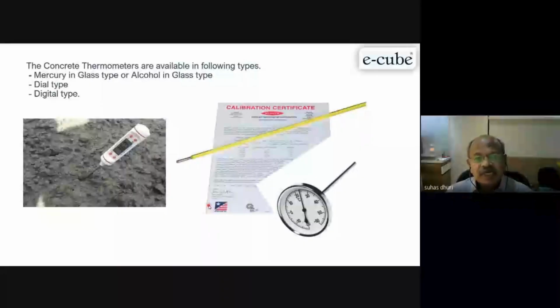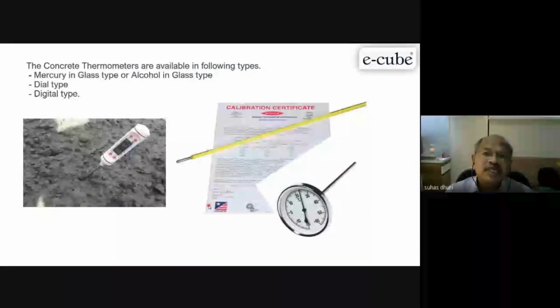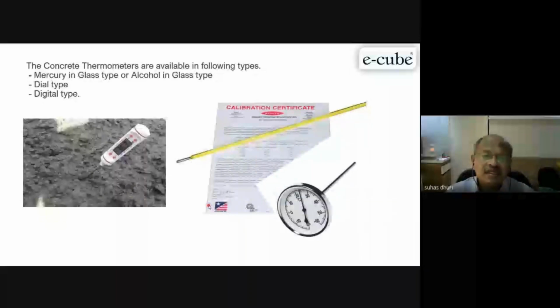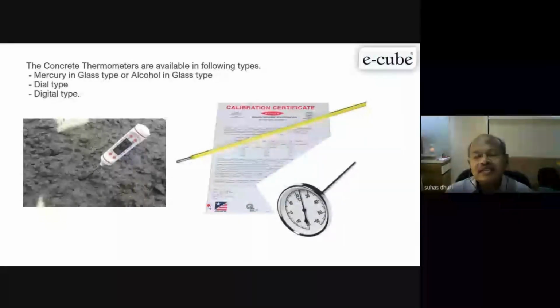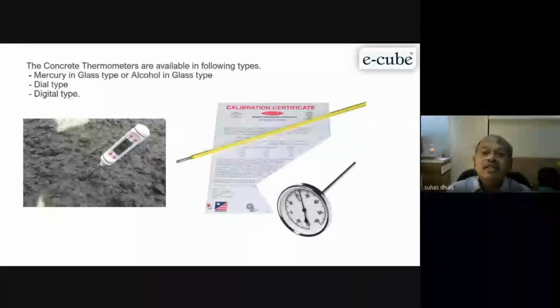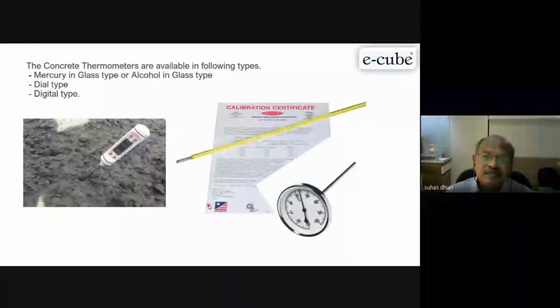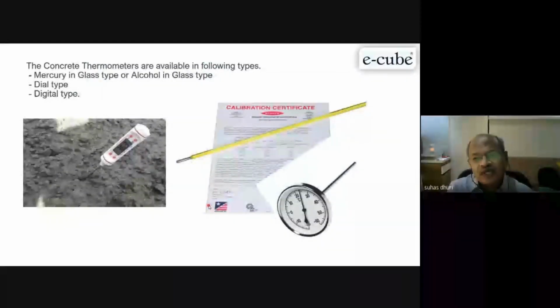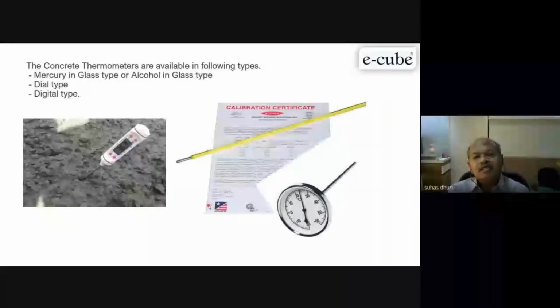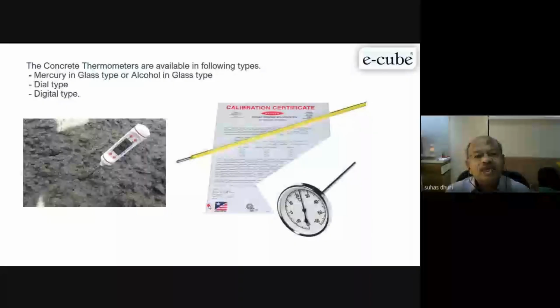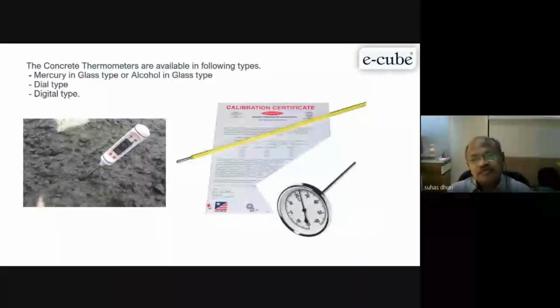Once the water demand goes up, you tend to use high range water reducing agents. It's an admixture basically, what we have discussed earlier. In that case, it's very difficult to get the slump. You always get a flow. Now one has to specify the flow, not the slump, because slump is slowly going out from the construction sites. We are getting only a flow today.